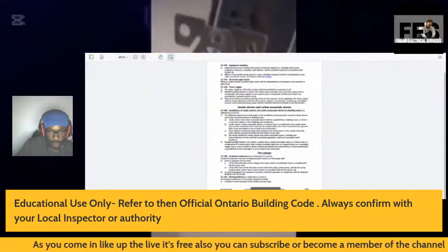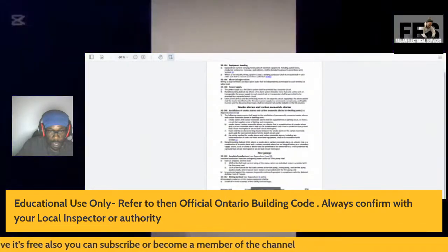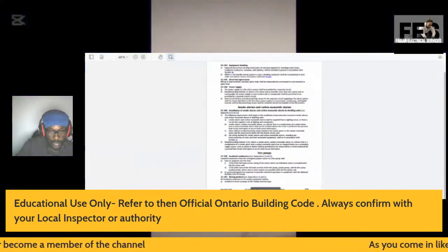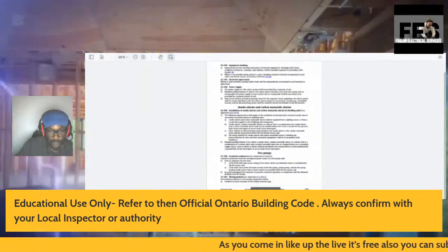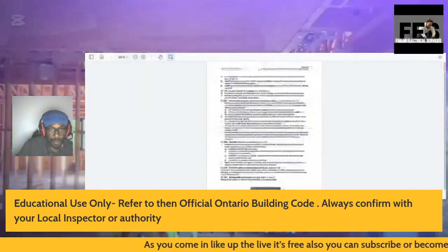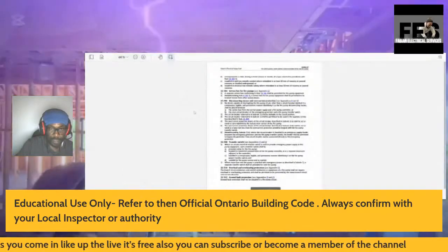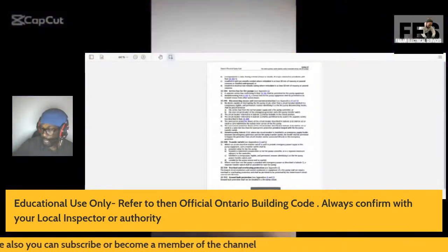Code of Canada. Wiring methods, see Appendix B and G. All insulated conductors to fire pump equipment shall be installed in metal raceway of the totally enclosed type. So again, this is section 32-00.